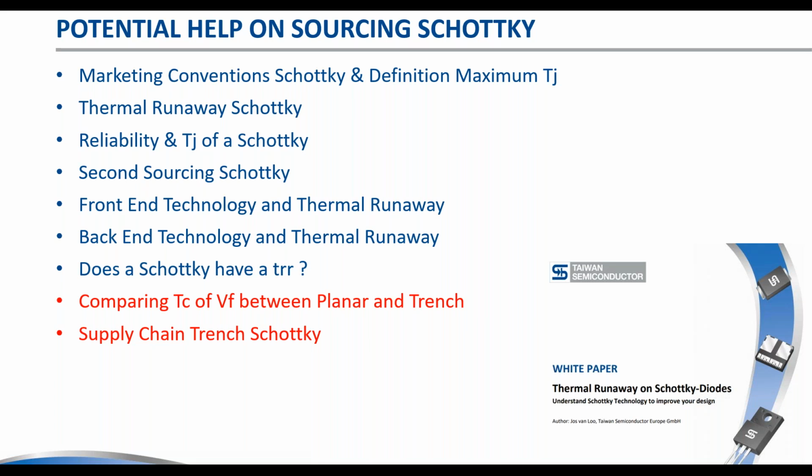We also wrote something about whether Schottkys have a TRR. There are no minority carriers in a Schottky, so essentially it doesn't have a TRR, but you can always inject them via the guard band. Usually a Schottky diode does not have a TRR, and we lived like that for the last 30 years.